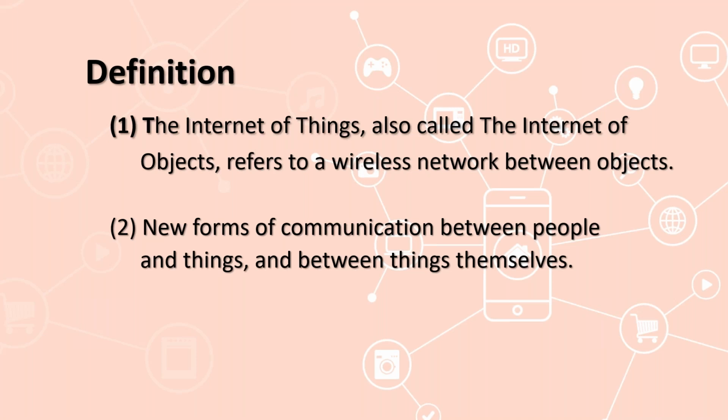And over there, we use Profibus, Ethernet, and different kinds of connecting cables to connect the MES, ERP, PLCs, and SCADA systems, and to connect to the server. Then we work on different protocols like OPC UA and MQTT to connect with the server and collect all the data. That will also be discussed in detail, the architecture of industrial IoT. Okay.